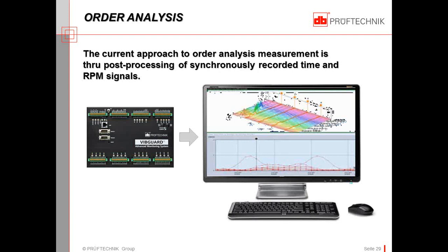So what does it do for us? Apart from avoiding things like smearing, the operator is going to get a very good picture of the equipment condition independent of RPM. So it enhances, well, let me say not truly independent, but we avoid the issue of smearing.